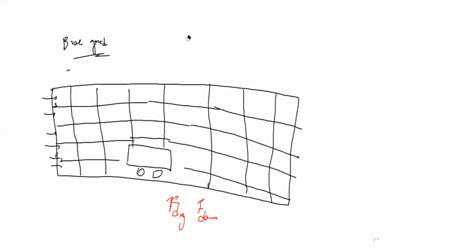What it will tell me is, create a box around which you want your mesh to be refined. So what I'll do, I will create a box of this much length. I want my mesh to get refined in this region. Then I will basically say fixed embedding, and I'll select the boundary like we selected there, that Ahmed body, whatever the boundary name is, this. Around this, I want fixed embedding.